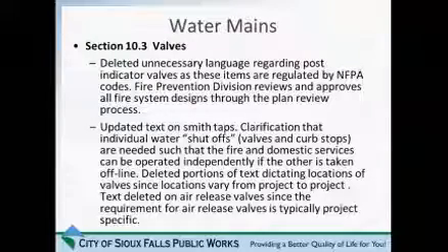We also had some text in there relative to locating gate valves or isolation valves in the distribution system. Previously, we had them located at tangent points on curbing, and I felt it was probably time to take that text out of there because we have to be a little bit lenient on where we put these, or have a little more latitude on the placement of these valves to facilitate future construction and try to minimize some of those valves that aren't really necessary by taking them out of the project.